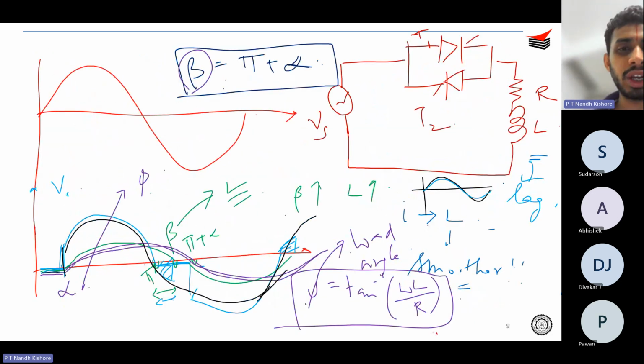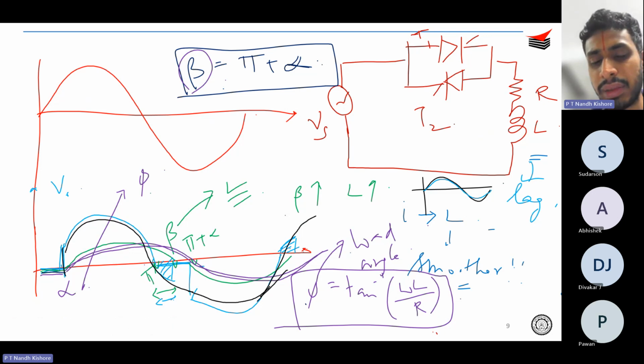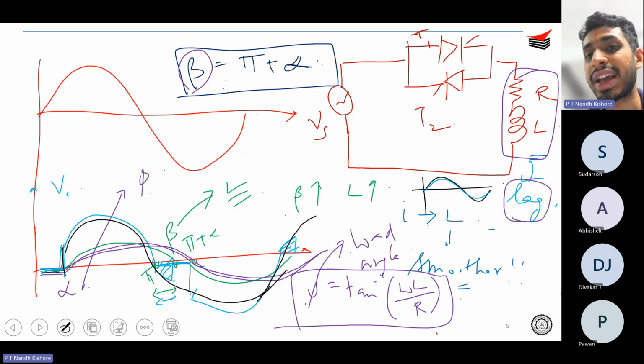Okay. So the point is we were discussing single phase AC voltage regulators having an RL load. So if you have an RL load, the load will have a load angle. Okay, so this is your load angle. Phi is actually tan inverse omega L by R. You can understand, right? It's just basic networks. So this RL will obviously give a lagging power factor, correct? It's going to have some lagging angle. So what is that angle? That is phi. Phi is basically tan inverse omega L over R, or tan inverse XL over R. It's your inductive impedance to your resistance of the circuit.